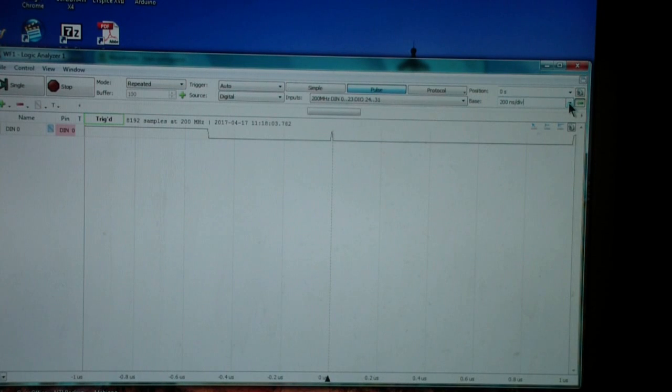Now let's go out to the horizontal limits of the unit, and you see it is actually catching that pulse, which is a pulse that's only, depending on where you measure it, but if you measure it from the 10% point on the rise to the 10% point on the fall, in other words, back to within 10% of ground, you get about 5 nanoseconds.